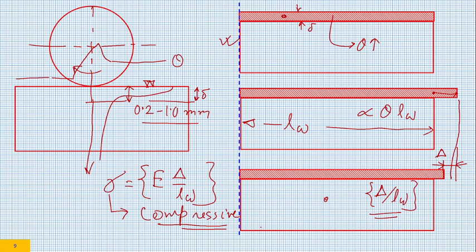And during the cooling period, this plastic deformation cannot be recovered. So whatever compressive stress develops during grinding reverses its direction, because that plastic strain cannot be recovered, and a tensile residual stress is